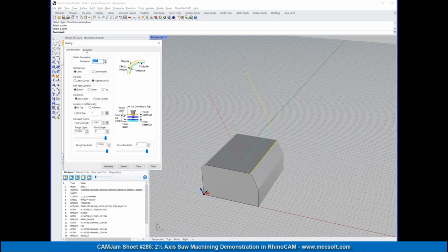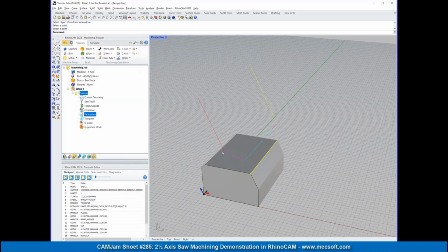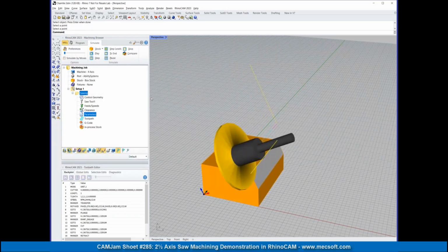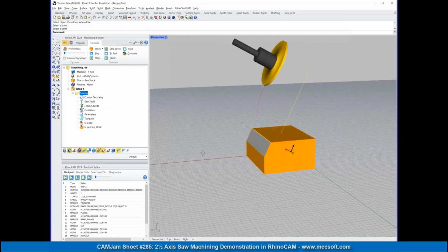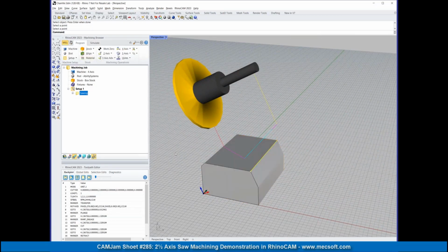And if I want to go a little bigger, let's say I want to extend it by 1 inch, but I want to go 0 degrees on the entry, and I'll say 2 inches if I want, and then I'm going to go 45 degrees just for the sake of it. So this is going to extend by 45 degrees out, and this is going 0 degrees coming in. Yeah, cool. Then I can simulate that. Cuts that out. Nice. That's cool.